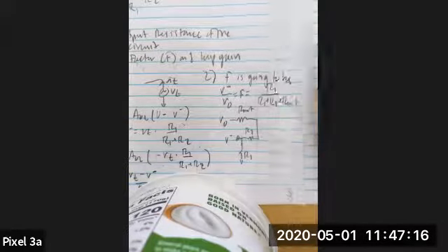Yeah, I think the wording of the homework question is finding the feedback factor from V out, but really we mean the output inside of the amplifier as opposed to the output outside the amplifier, because the outside output is not particularly useful if we have some finite R out inside of the amplifier. That'll attenuate it further. So hopefully that makes sense.